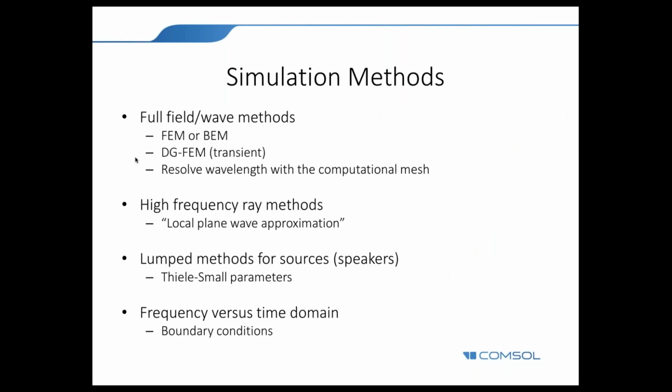There are different methods in COMSOL Multiphysics that can be used and combined to get an in-depth look at this acoustic simulation. There is the well-known finite element model or the boundary element model that can be used. There is the so-called discontinuous Galerkin finite element model if you would like to do transient simulations. And you can use the ray optics or the ray acoustics feature that we will use in the second model, where we want to solve for higher frequencies.